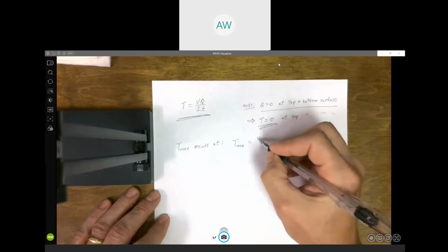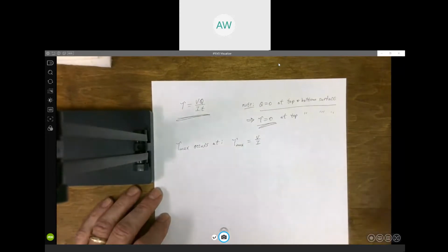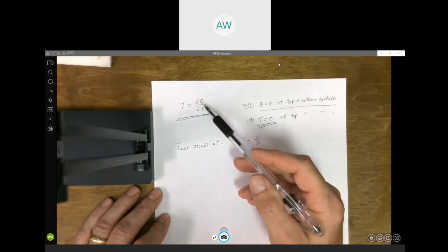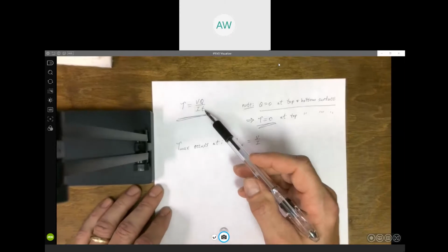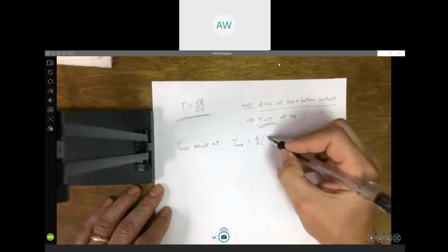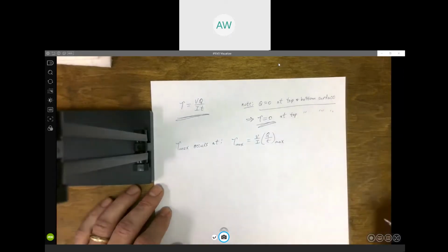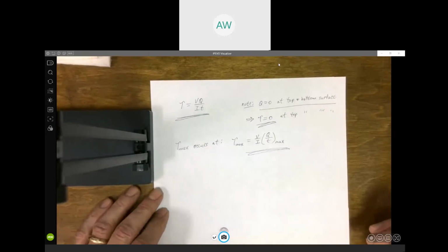V and I are constant with respect to the cross section. Right? The shear force V is the shear force acting on that entire cross section. I is the moment of inertia of the entire cross section. What changes if you move to a different point on the cross section is obviously Q and possibly t. So it's going to occur where this ratio, Q over t, is a maximum. Right, that's where you're going to get your maximum shear stress.